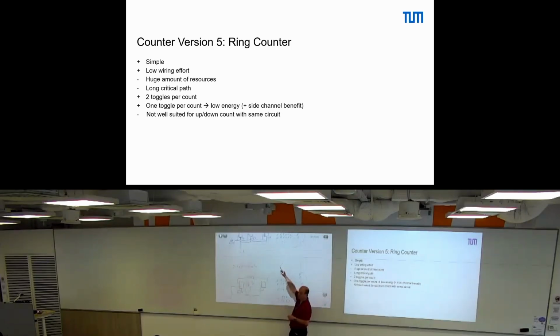For the ring counter, at that point here, we would have an overflow, because if we had 0, 0, 0, 0, 0 and a 1 at the very last, the next one would be 1 and the rest zeros, so we would be back here. So for the Johnson counter we spend 1 additional inverter, that's our additional cost, but we save at the same time 1 flip-flop if we want to count to the same number. So effectively the length is overall halved.